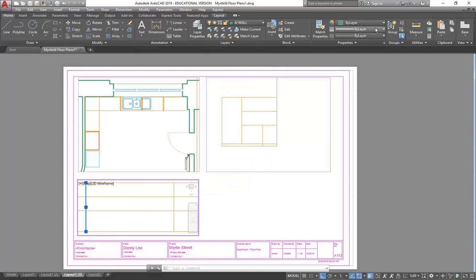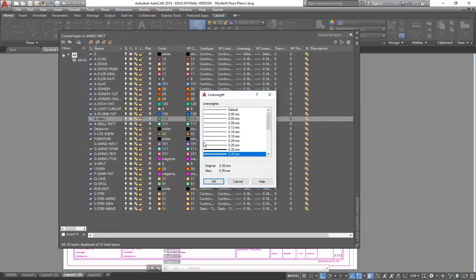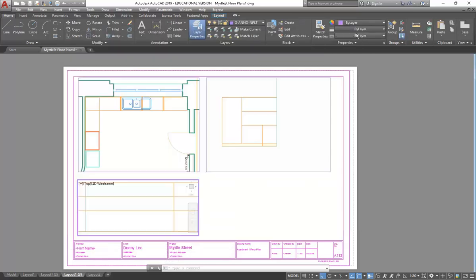So I've changed my wall layer, but again, I have to check the line weight there. What's going on there? Okay, so they've got theirs at 0.5. This is again from Revit, so I'm going to change my wall setting to match that. So my walls look the same. Just a few little workarounds like that when things come from Revit. And so then what you might be thinking is, how do I make that line up exactly?